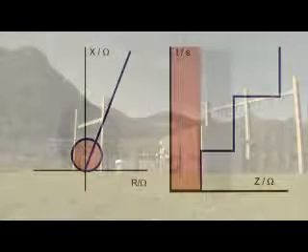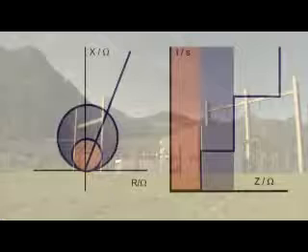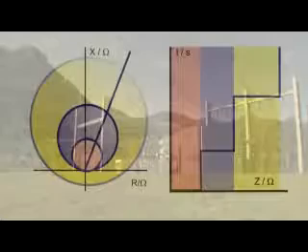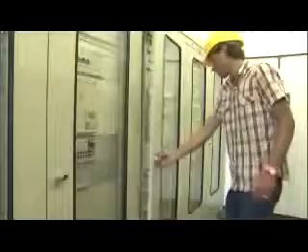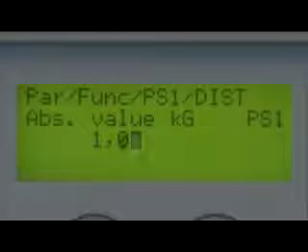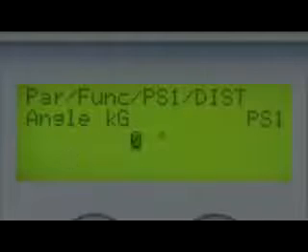These relays identify the zone in which the fault occurs by measuring the impedance of the fault loop and comparing it with the impedance represented by the zone setting. Since the impedance of the ground differs from the impedance of the conductors, the relay must apply a correction factor to determine the distance of a ground fault from the relay. This factor is usually called the K factor, the ground impedance matching factor, or the residual compensation factor, depending on the manufacturer of the relay.